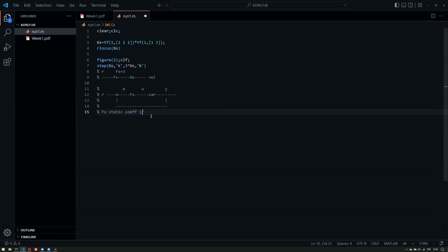It could have an integrator, for example, or a derivative element, but it doesn't have that. We have none of that. We just have a coefficient, and we want to determine what happens to the system in the closed loop, because that's our desired scenario, if we change this gain and how we change this gain. So therefore, the root locus can be used for that.